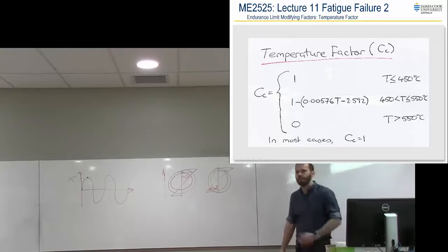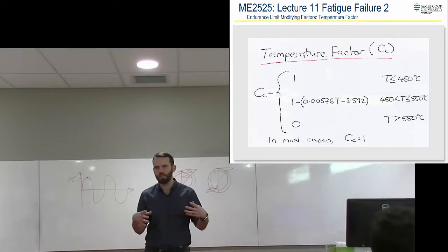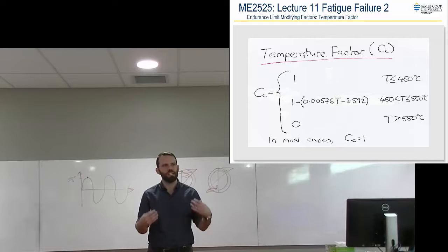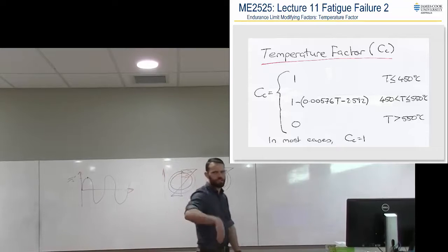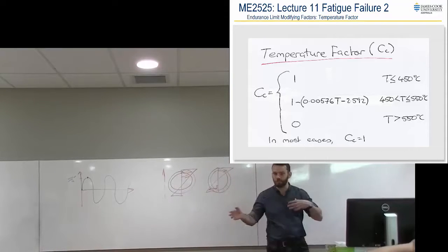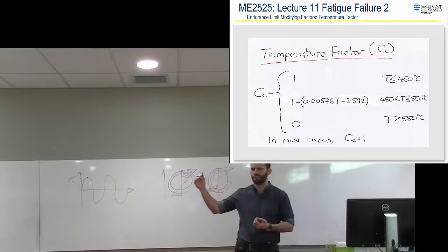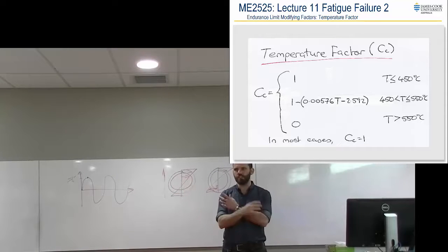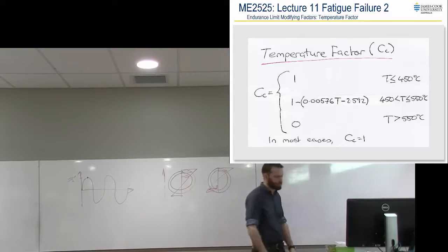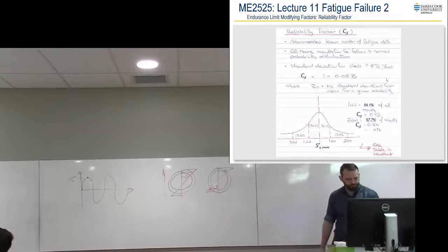Because any hotter, even though you're not molten, even though it's not changing in that respect, it is changing the crystalline structure, which changes the way that force gets carried, and it changes everything. So after those lines, you're annealing and getting rid of stresses and things like that. So you can imagine that if that's the sort of temperature you need to get rid of stress and residual stress, it's also the sort of temperature that'll just turn it into a plastic mess and allow you to do anything to it.